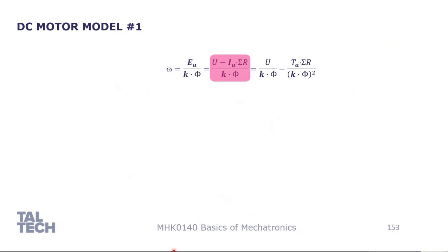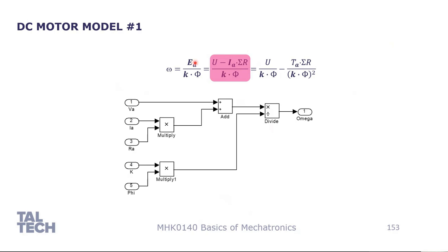Having this equation, we can simplify some parts. If you would like to describe how the system is working without the mechanical part, we can take this middle equation, the dependence on the current, and by adding variables to our model, we can calculate the angular velocity.